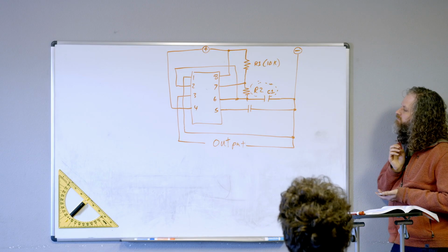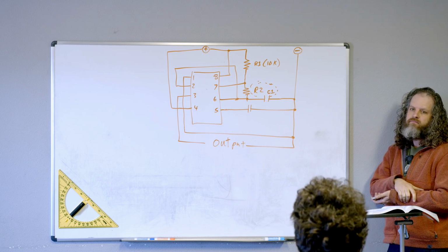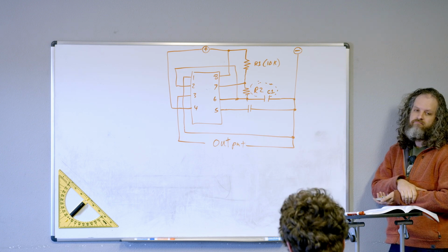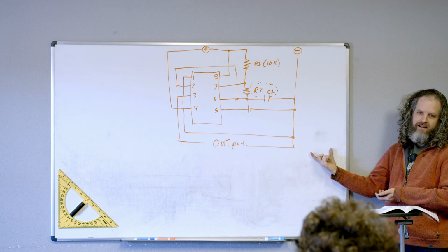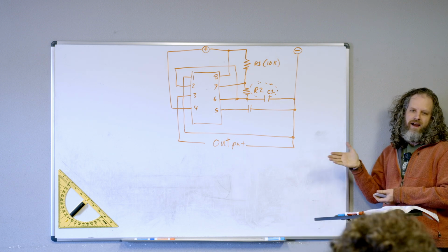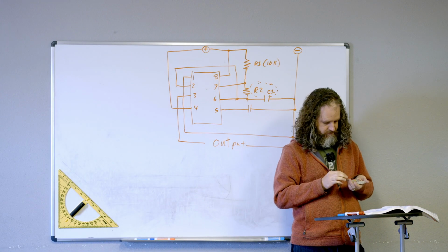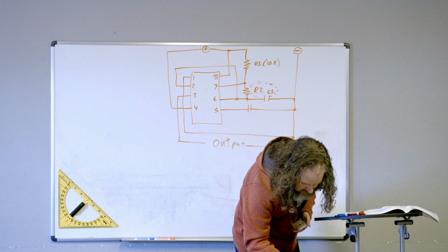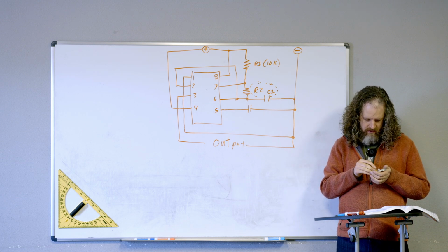Is it 3 connected to the LED to the resistor to negative, or 3 to the resistor to the LED to negative? It doesn't matter. Because that's all one loop, one branch, right? It's the same current going from this node to that node. So whether you do it before or after, it does the same. Okay, okay.